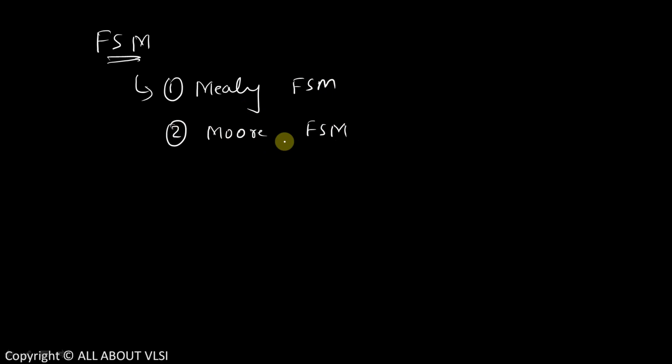Let us try to understand what we mean by Mealy FSM and what we mean by Moore FSM in great detail. Let us see the exact difference. In the case of Mealy FSM, your output is dependent upon both the input and the current state of the circuit.